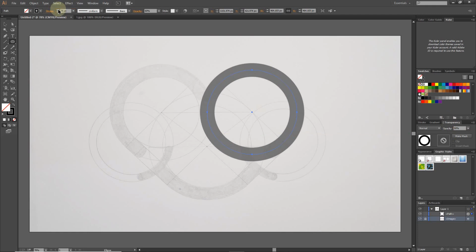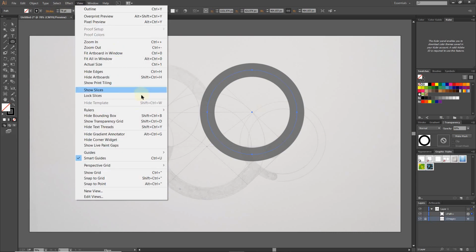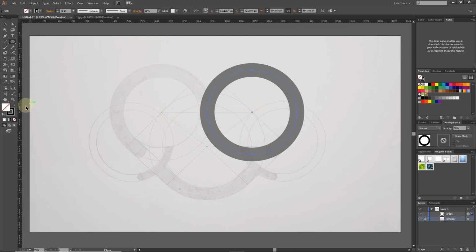So now we need a center line so that we can have a symmetric geometry. For this purpose, simply go to View, then go to Rulers and select Show Rulers. And drag your ruler towards this quadrant like this. And now this ruler will act as a center line.